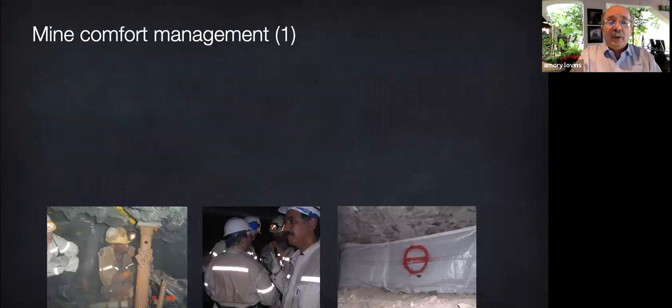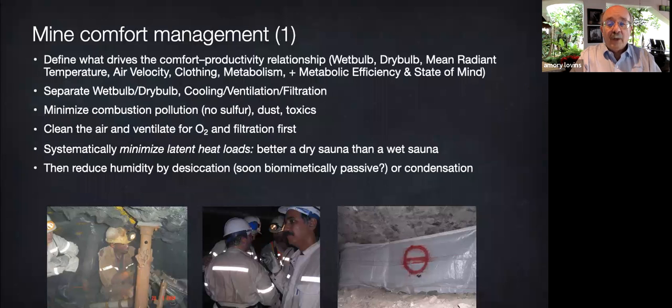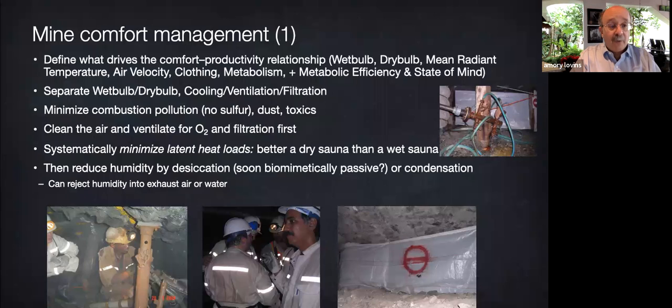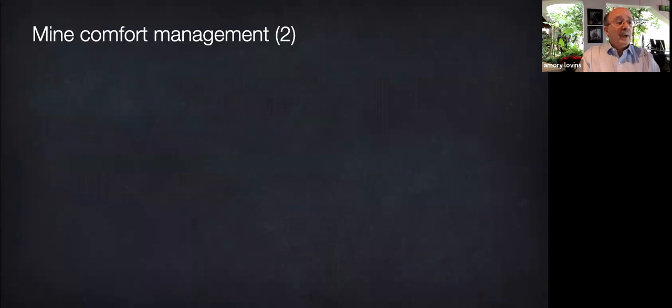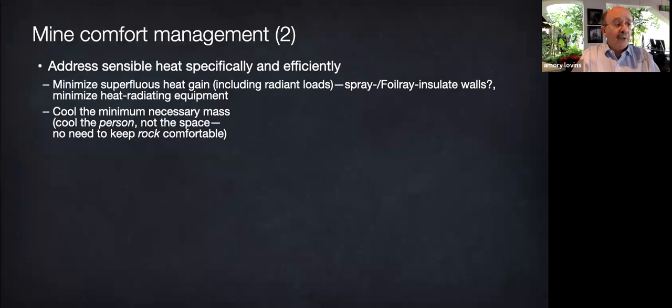Now, we didn't yet know how effective radiant cooling could be, but now that could offer an even better option. Now, to moderate the sauna-like conditions so far underground, after minimizing unnecessary humidity, all of which was introduced, but not very thoughtfully, we would minimize the heat gain from the rock that's hot underground and from the mining equipment.